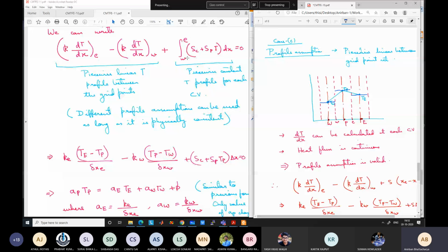Let us take out Sp. What is left is west to east T into dx. So you need some profile of T to calculate it. If I take that T remains constant, I can take T out and it will become T into delta x. And that is what we are doing.